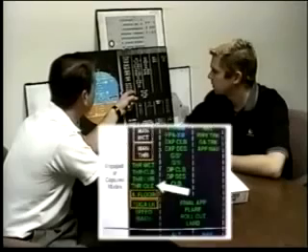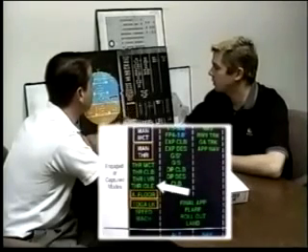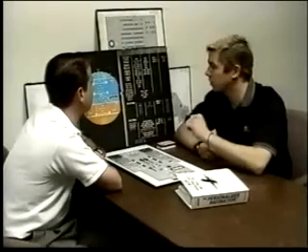Moving down to Thrust Idle. Thrust Idle just means that the auto thrust has been commanded to idle thrust and idle thrust only. It doesn't mean that the thrust levers are in the idle detent. Typically, the way we operate this aircraft, the thrust levers are going to be in the climb detent. But the thrust has been commanded to idle and nothing but idle.